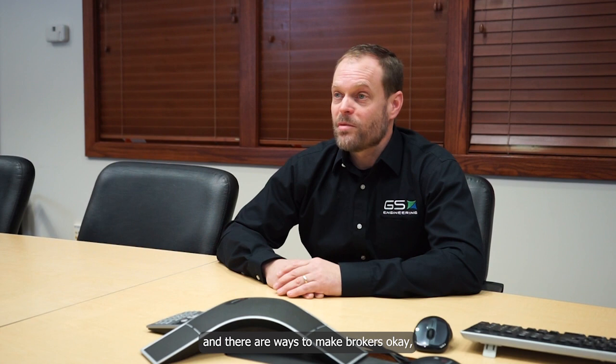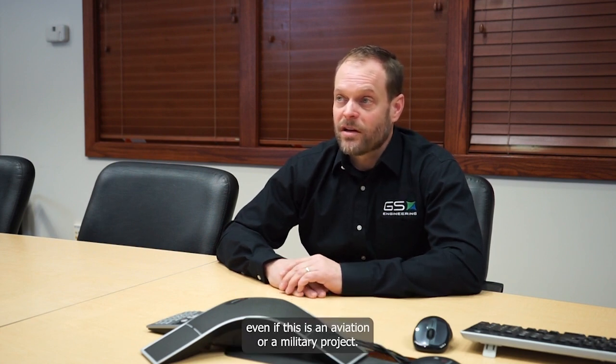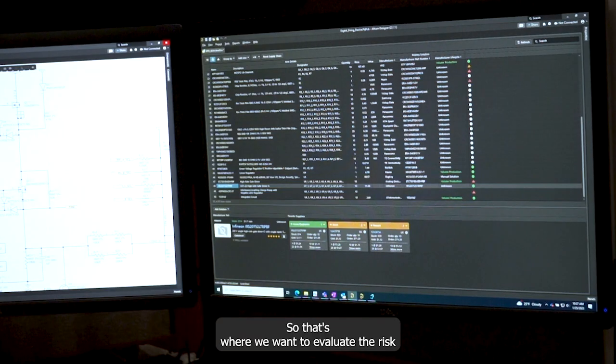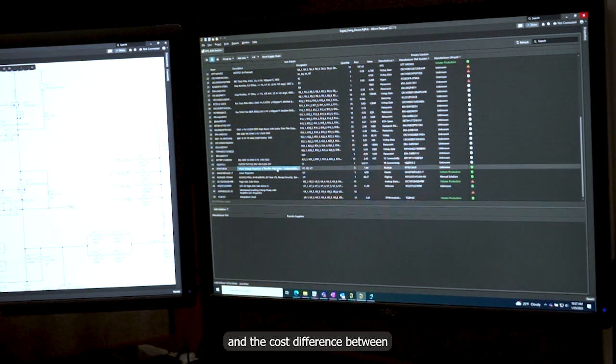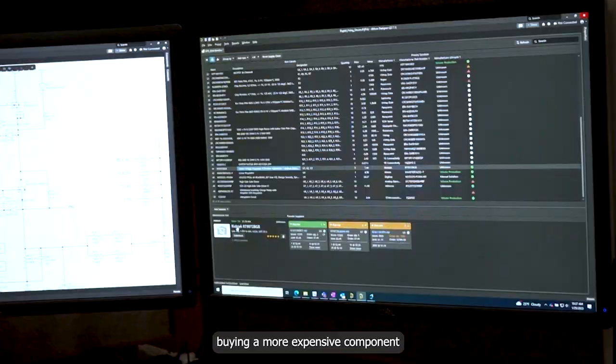The next step would be to look for alternative suppliers of parts. And there are ways to make brokers okay, even if this is an aviation or a military project. The downside is typically that you are increasing your component cost significantly. So that's where we want to evaluate the risk and the cost difference between buying a more expensive component or having to change your board design itself.